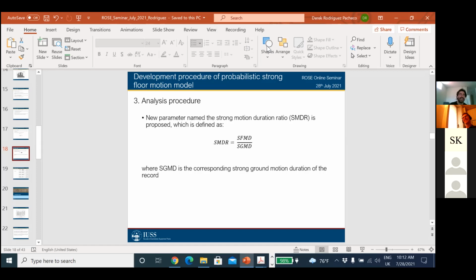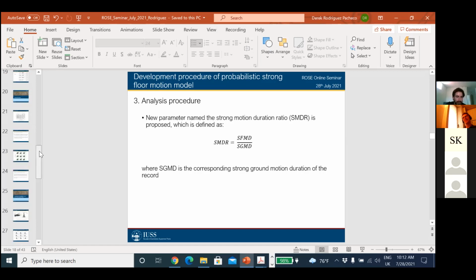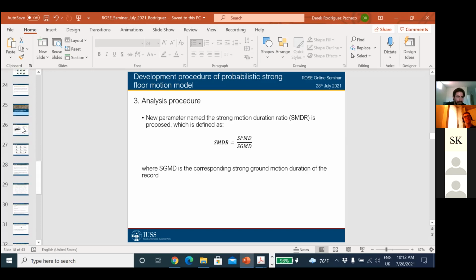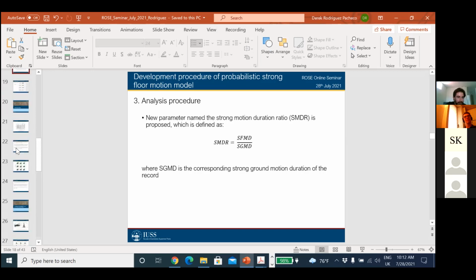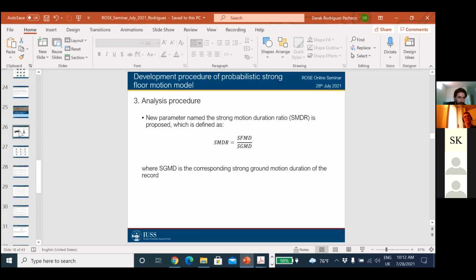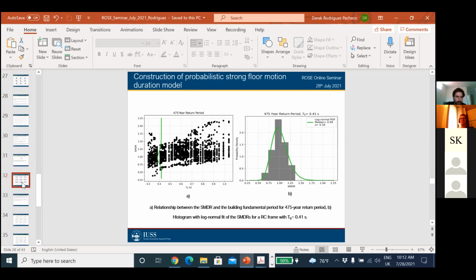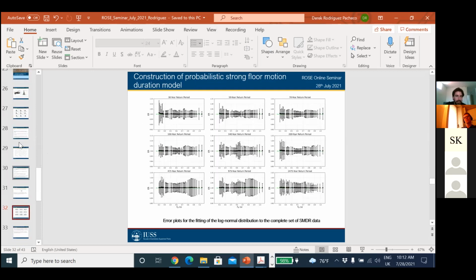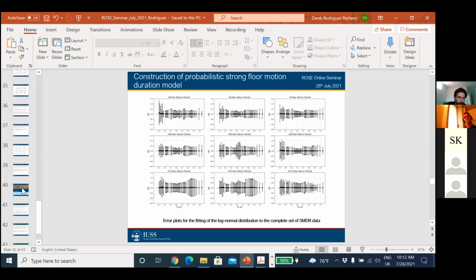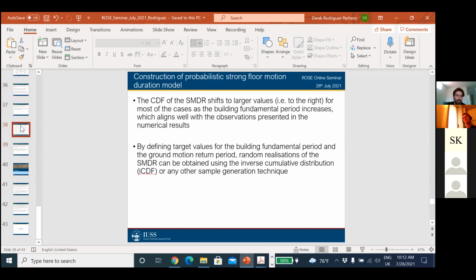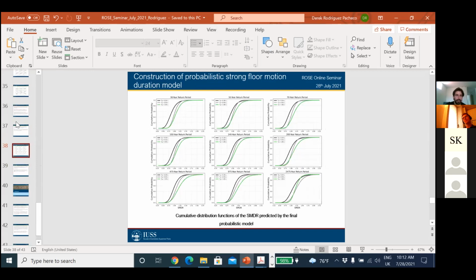In the structure. Well, if you see, let me show you some plots here. No, I don't have that plotting here. But one thing that you can say is that as you have higher ductility demand, you have higher degradation, and in the structural system your period will lengthen more or less.